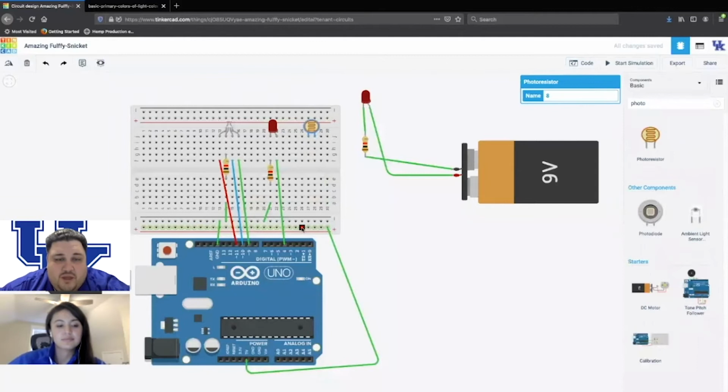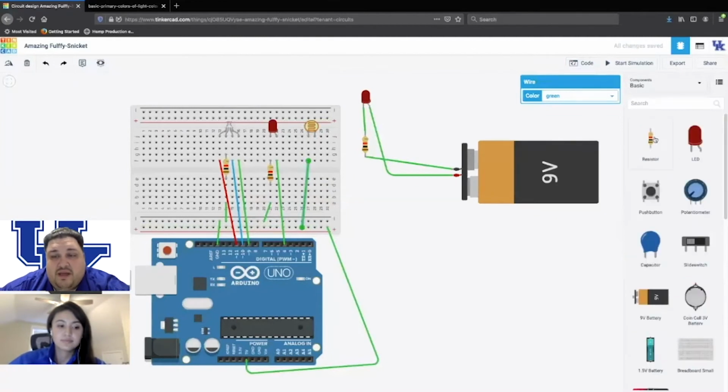And then we're going to connect one leg from the positive there to the leg on the left. And then I'm also going to need to grab a resistor. So I'm going to drag that. I'm going to put it over the middle junction there to jump that. And I'm going to change the resistance to 10 kilo ohms. The K stands for kilo. The little horseshoe stands for ohms. Connect the bottom leg to the negative terminal.